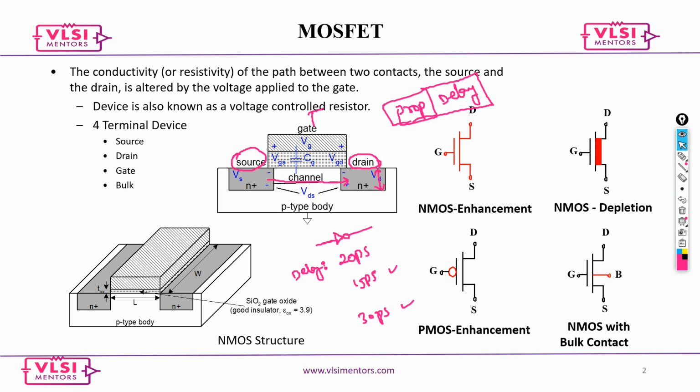Scaling down the channel length. Okay, so you have to reduce the channel length. How can we reduce the channel length? There's a term called width to length ratio. Exactly. So now you have to understand, any transistor that you talk about has a W by L ratio. There is something called width, and then there is something called length.